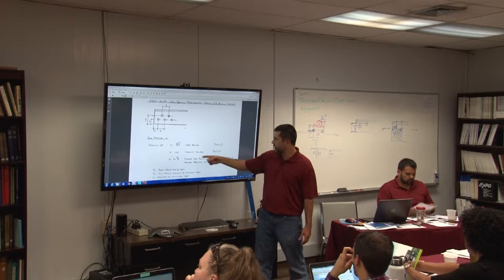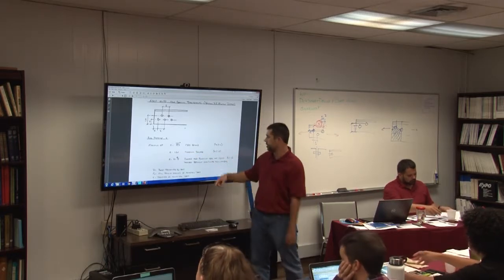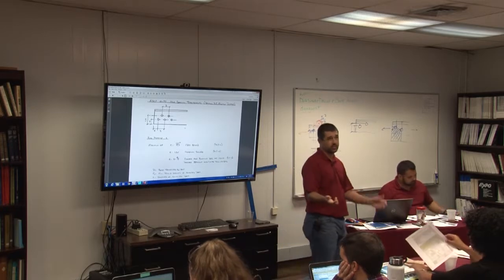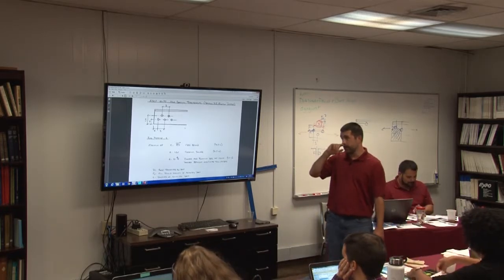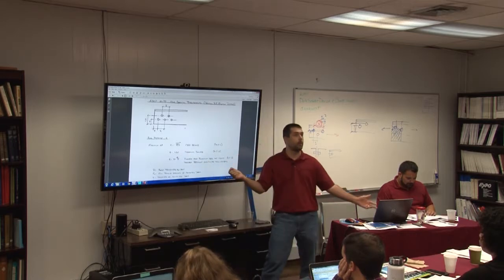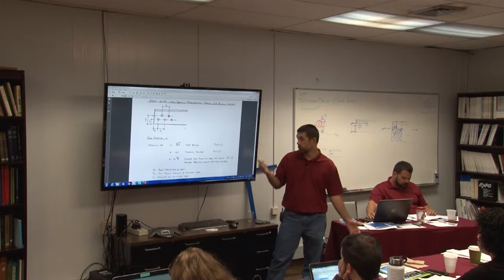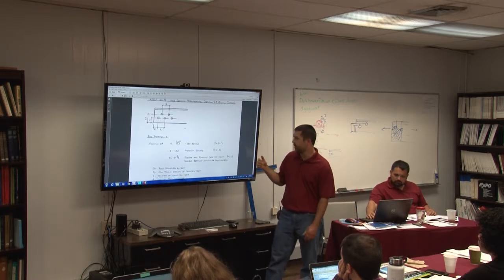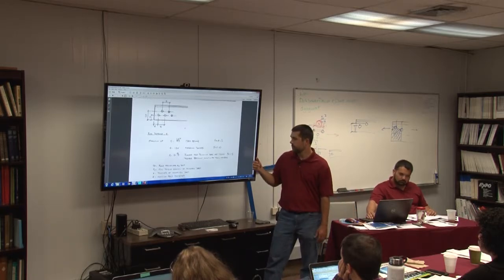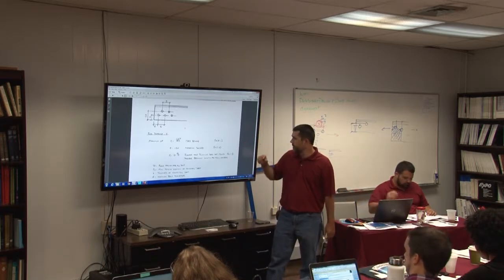I mentioned that there's this 1.3D end distance limitation. That is basically a historical success thing. Somebody a long time ago said, this seems like a good number, I'm going to use it as an end distance, and they've had no problems with it. So it got incorporated into the standard. That's where it came from, and they tell you that in the commentary. They thought of testing too, I'm sure. Yeah, I'm sure, right.